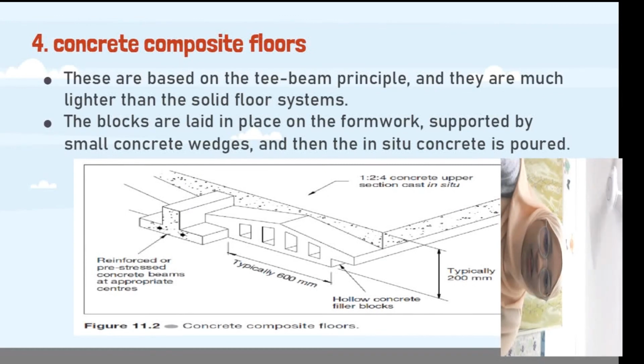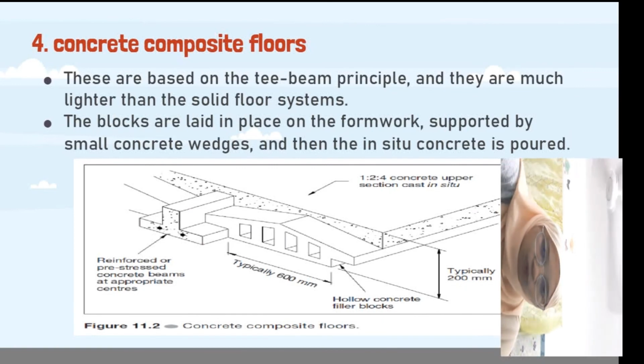They are based on the T-beam principle, and they are much lighter than the solid floor system. The blocks are laid in place on the formwork, supported by small concrete wedges, and then the in-situ concrete is poured.